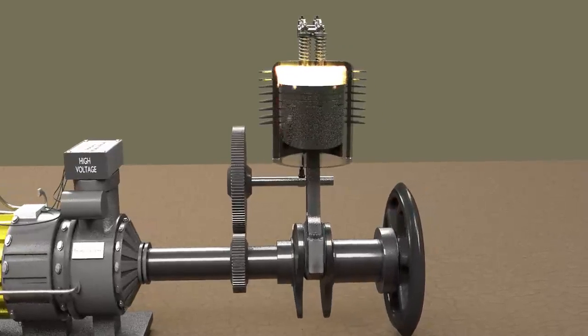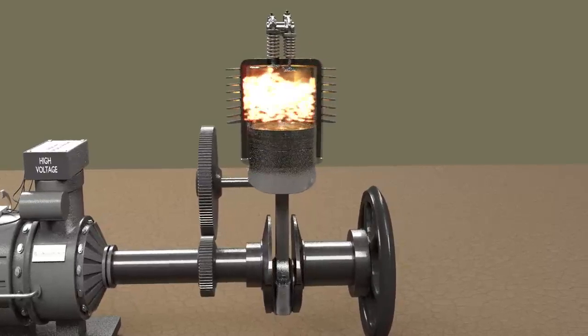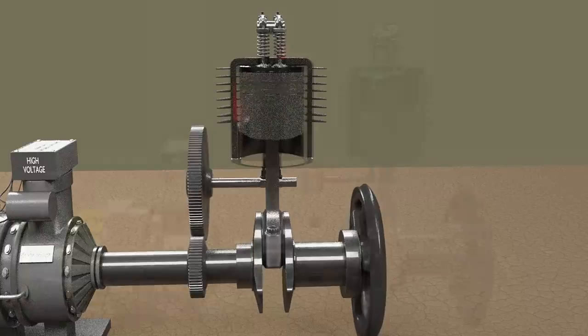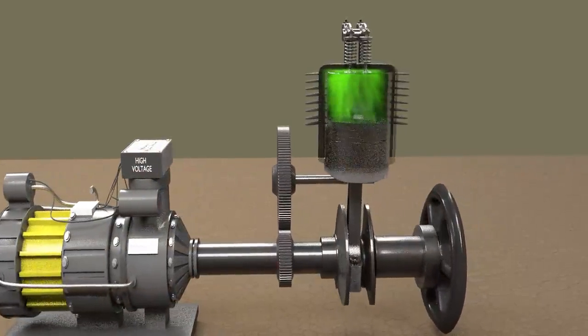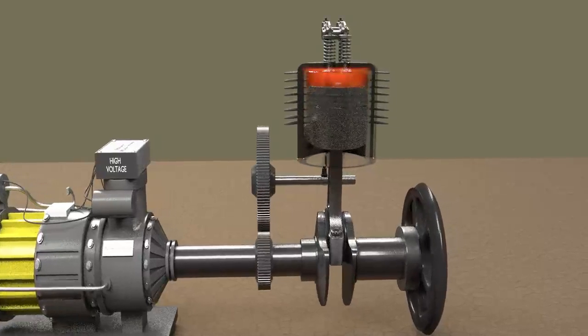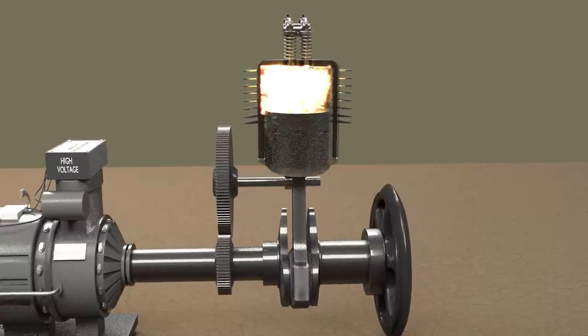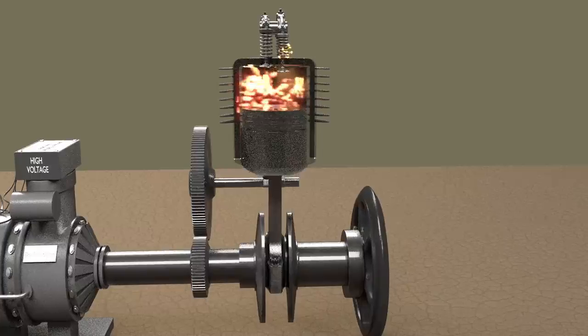When excess energy is developed by engine during power stroke, the excess energy is stored in flywheel with overall smaller acceleration. And when energy is required by engine during compression and other strokes, the energy is provided by flywheel by decelerating itself by a small amount. Thus flywheel reduces the fluctuation of speed of engine.